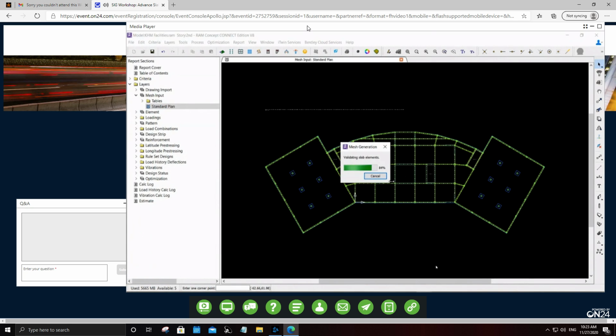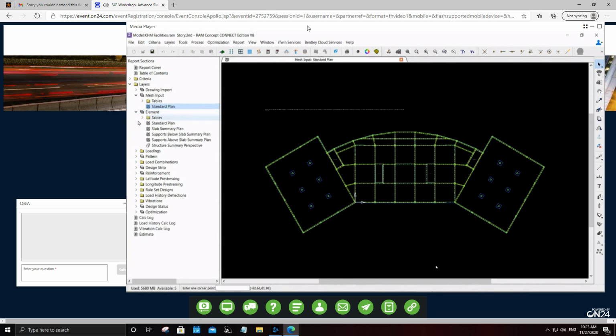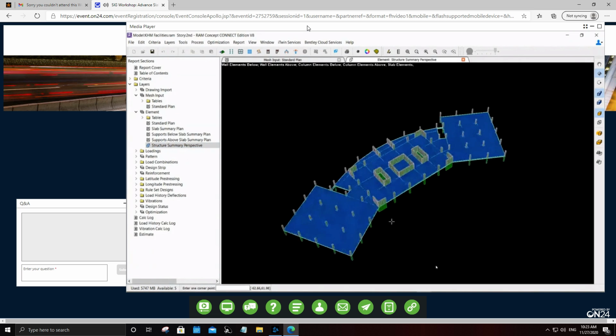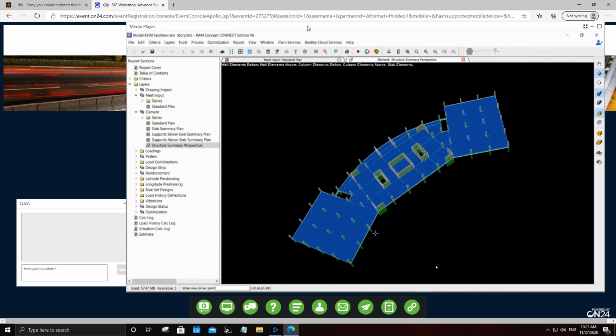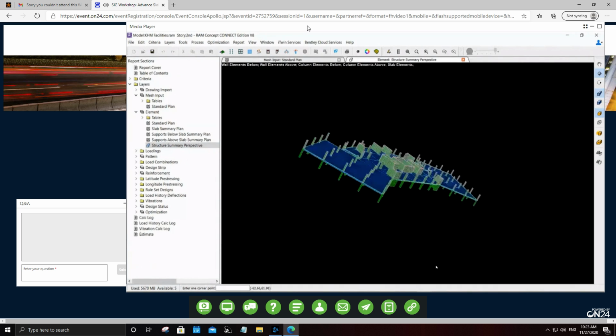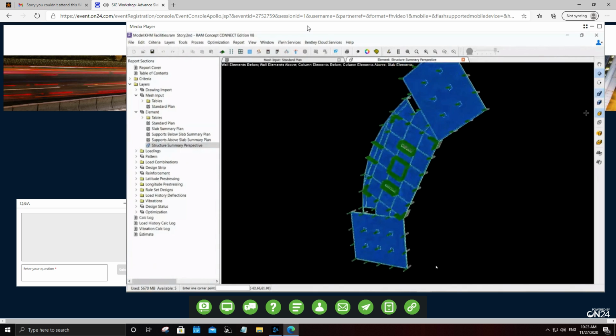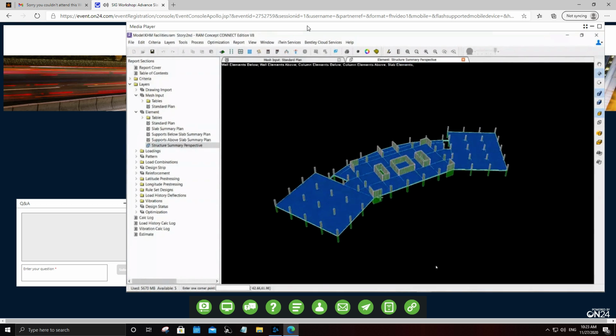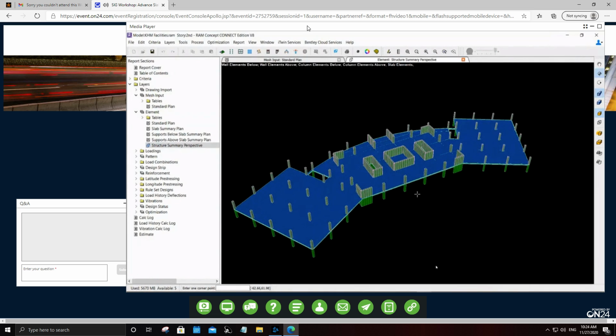And as I said, though it is analyzing a slab only, it is still a 3D FEM analysis program. So by this diagram, you will be able to understand what's going on here, what we are going to analyze. And you will see that all the drop caps and the beams that we have in the middle slab are also completely imported from RAM Structural System to RAM Concept.